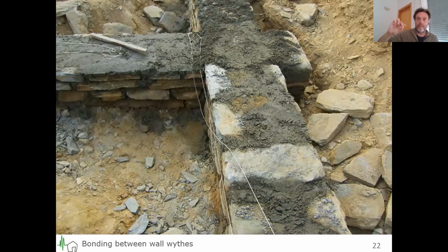So this is what we did. And I already said, well, okay, we make a lot of bonding, so through stones. We invested in cement mortar, but now the question is, should there be something vertical here? And we feel there shouldn't. For two reasons. Reason number one is that this is a very heavy building. And it means that when an earthquake hits, a lot of lateral force is being generated. Is one steel bar going to resist all that lateral force? We doubt it. Is it going to give the ductility we need? We really doubt that one bar is going to do that.